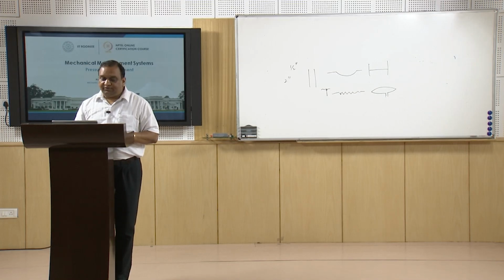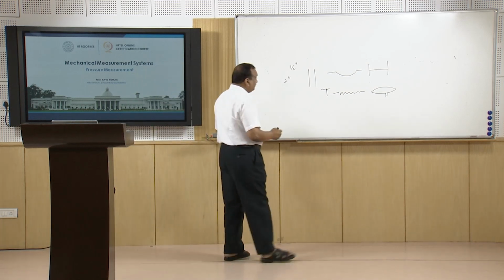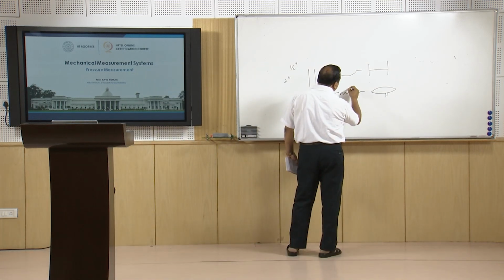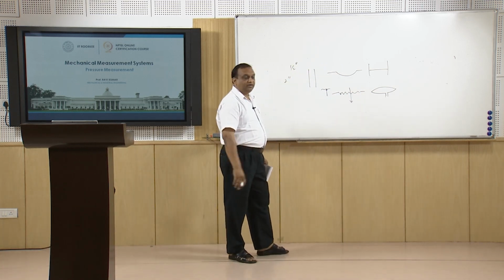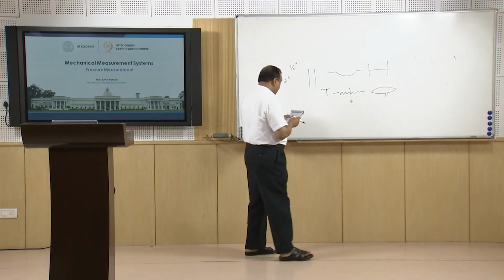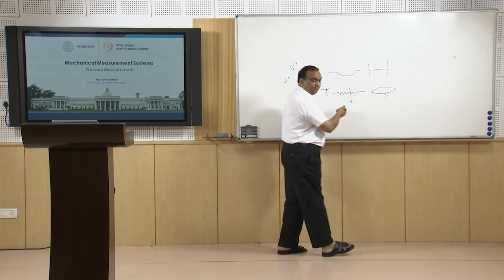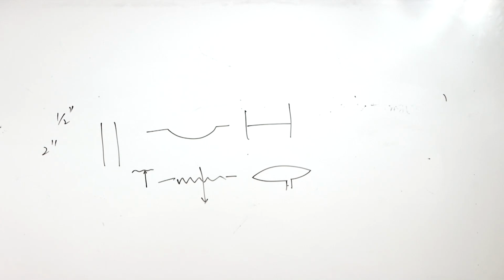The corrugated diaphragm, especially, is used to improve the performance of strain gauges. It is used for large size of strain gauges. And this corrugated diaphragm also increases the linearity between the load applied and the deflection. And it causes less stress, it is obvious, but the dynamic response of the corrugated diaphragm is not that good. Okay, so it is normally used where the static signals are there. It's the corrugated type of diaphragms.